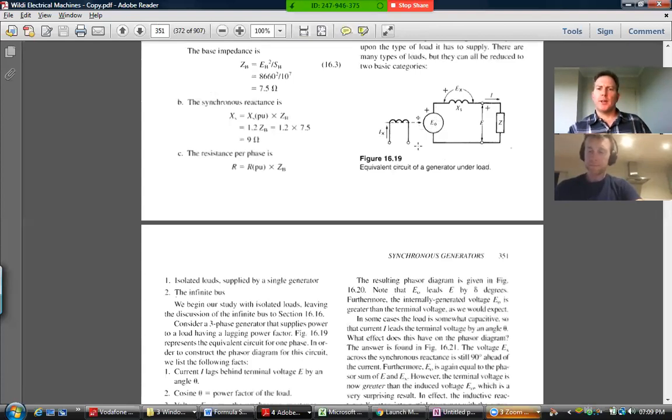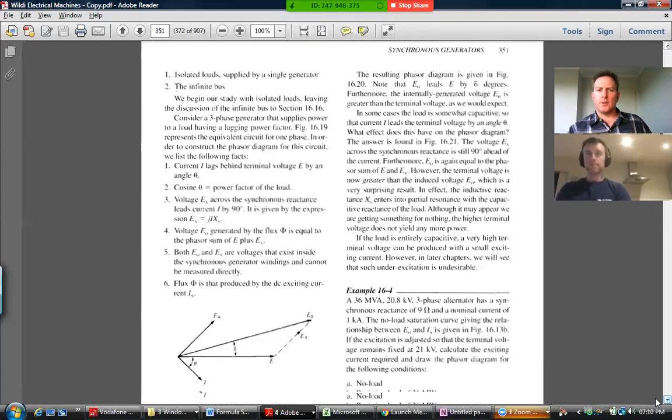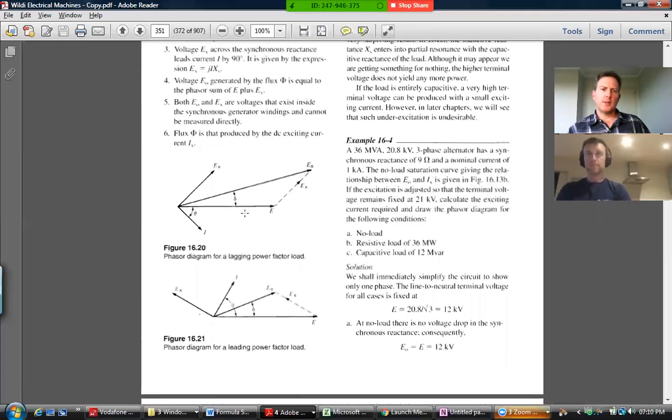By simply playing with that, we can force any E0 we want to be established within limits. Of course, there will be saturation at some point. And in doing so, we can achieve whatever voltage we want over here. So when you analyze, don't forget to convert to per phase, and then key things again, summarizing.